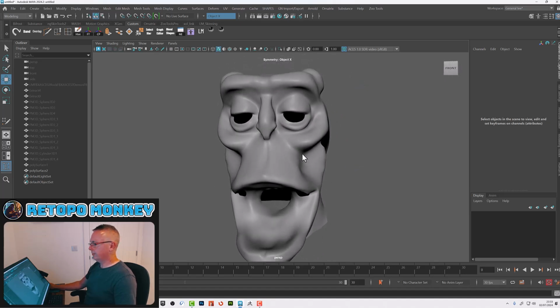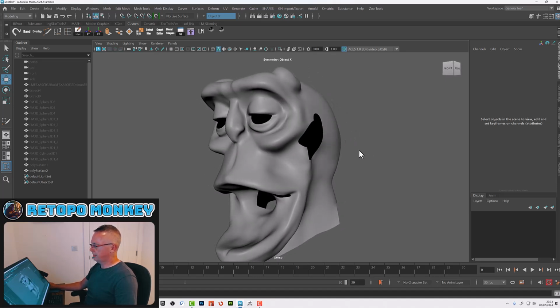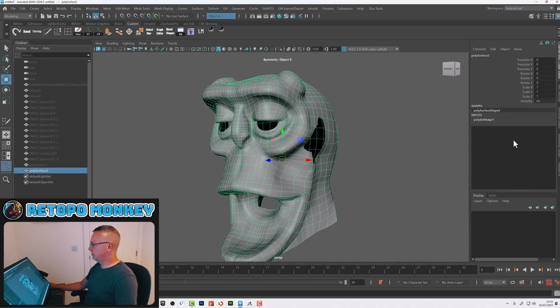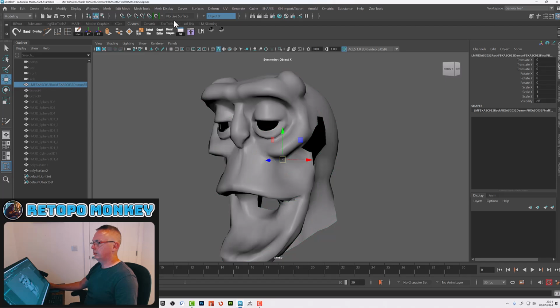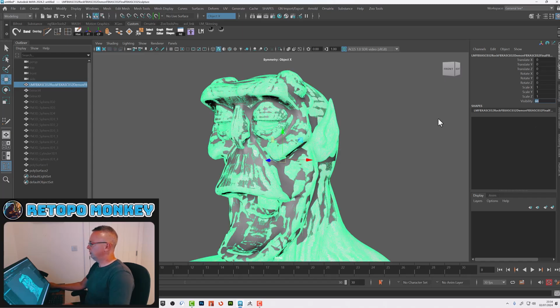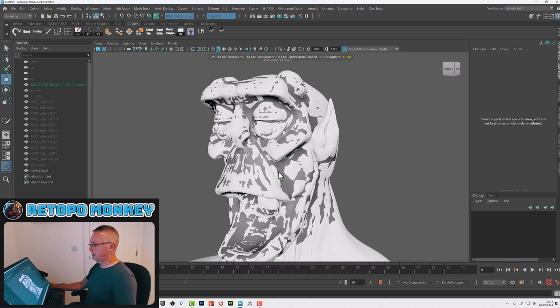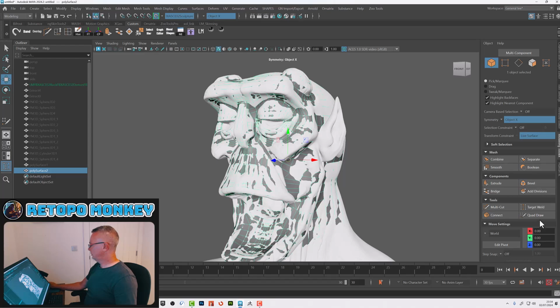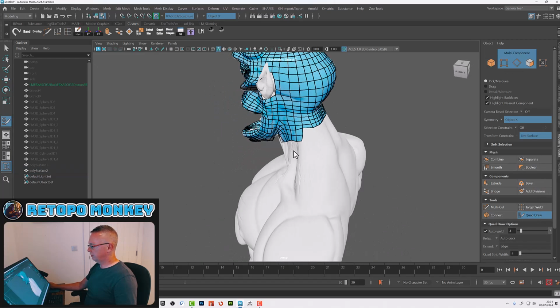So fill in these other components, extrude the throat and the eyelids, and then it will be ready for rigging. So hit 1 on the keyboard, go back to your high res, turn on the visibility again, number 1 on visibility, make it live so it goes green, select the poly surface, modelling toolkit, quad draw, and back into it.